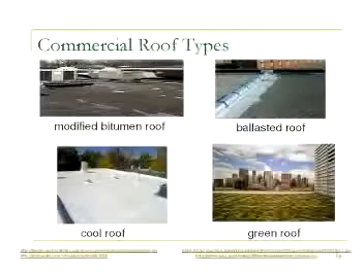So this is one example where we've used this tool, and this is to look at what's the advantage of, in fact, changing roofs. Those of you who are in the energy field probably have heard a lot of talk about so-called cool roofs. So the idea is, for example, in flat roof commercial buildings where we typically use a bitumen roof system or a ballast system where the roof is very dark and absorbs solar energy, the thought is, well, instead of doing that, let's put a reflective surface to reflect that solar energy, or put a green roof on.